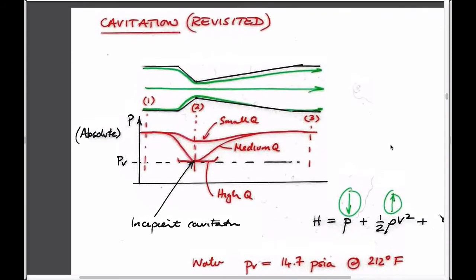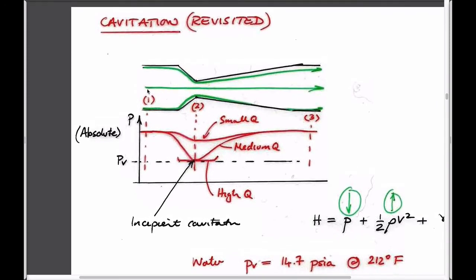But the principle is relatively straightforward, and that is we'd like to know what the velocity in the pipe is here. We know that the velocity in the pipe will be different here. It'll be higher. And so what we can use is the idea of Bernoulli. We could draw, what would it look like? If we drew along the length of this, these components: we have elevation, we have pressure head, and we have velocity head.